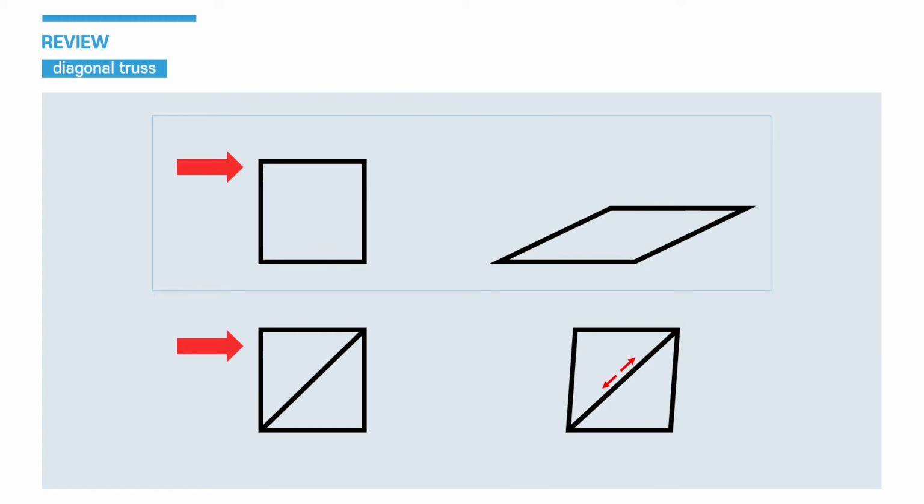A structure consisting of only horizontal and vertical members is easily rotated and consequently destroyed in the direction of force, because it cannot resist the moment at pin fixation. Therefore, additional structures were needed to reinforce them. The structure is truss. Truss is a triangular structure that forms additional tensile and compressive stresses on the structure, further stabilizing the structure.